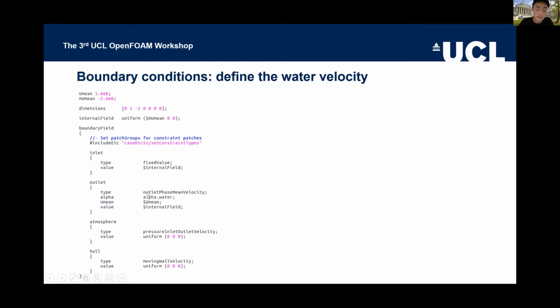And there is this outlet function, which is quite important. It makes the outflow water flow the same as the inflow water flow. If the mass of the outflow water doesn't equal the inflow water, it can cause the fluid surface to increase or decrease. It's quite crazy in that case, and it happened quite often. So this boundary condition defines the outlet water flow to always be the same as the inflow, so the water line can be kept at the constant value that we want.